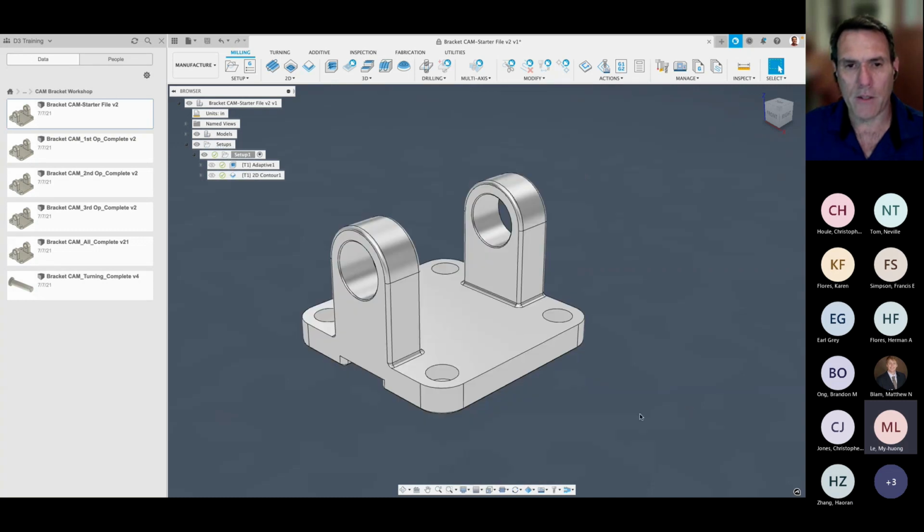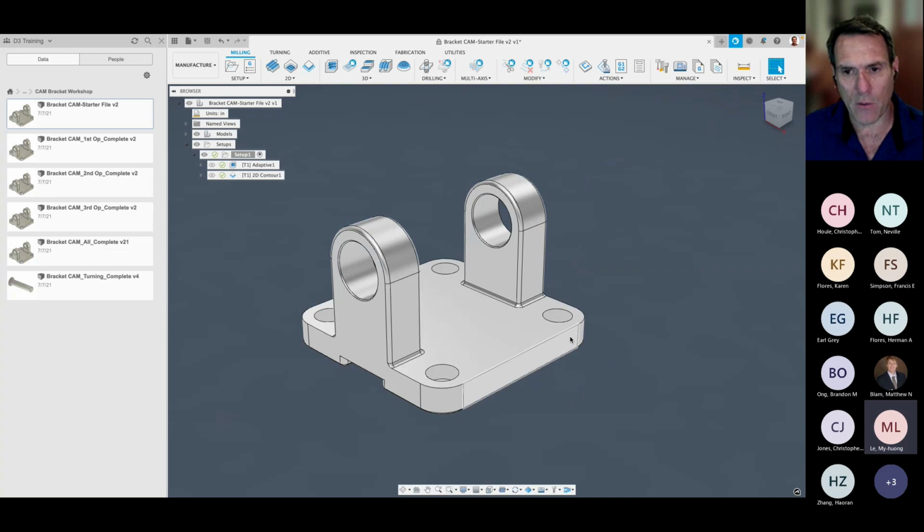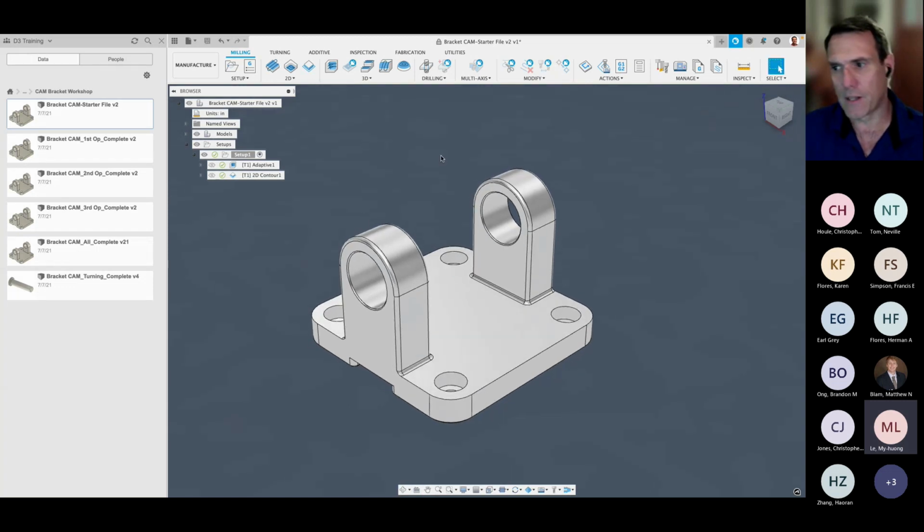Yeah, it's okay. I was going to point out on some of the imagery, you can see that when we're running the toolpath, there are edges that are not quite coincident. That is where we have additional material. For example, we left our roughing 15 thousandths of an inch all the way around everything and on top of everything. So now we need to start clearing some of that off.